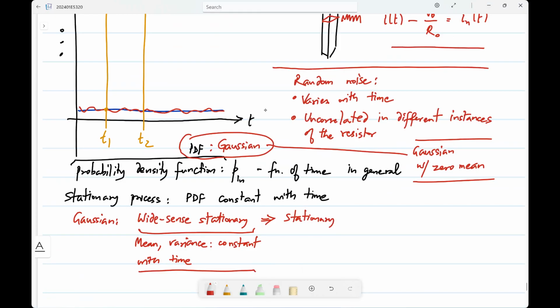I have a circuit with resistors, capacitors, all kinds of components, and I have a sinusoidal signal. What's the method you would use to analyze, as opposed to when you have a DC voltage? What's the difference? Basically, you use frequency domain analysis. Why do you use frequency domain when the signal is time varying?